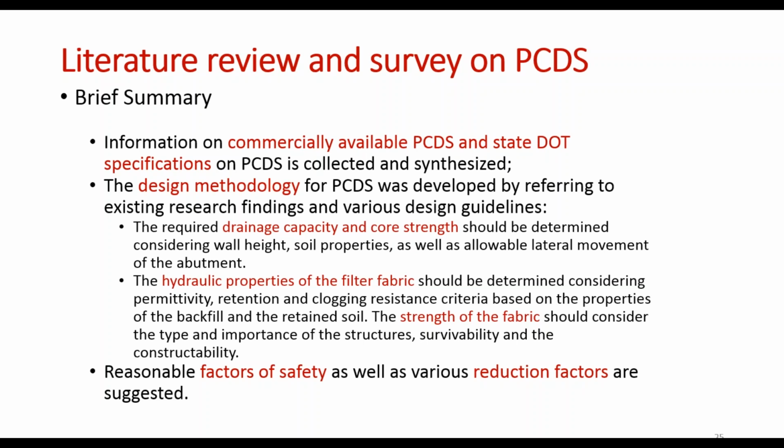And the hydraulic property of the fabric should be determined considering the permeability, the retention and the clogging resistance, which can actually be obtained based on the site soil properties. And the strength of the fabric should consider the type and the importance of the structures, since we are dealing with bridge abutments and the wing walls.